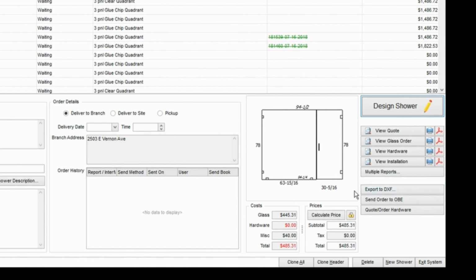That is when you can actually create a digital file of the glass sizes that would be designed for importing into glass cutting software, into CNC glass cutting machines. Tempering companies sometimes love it if you send them a DXF. They don't have to then program it. They just take the file you sent to them, put it into their machine, and away they go. It's automated cutting that takes a lot of work out of preparing a number of pieces of glass to be cut.